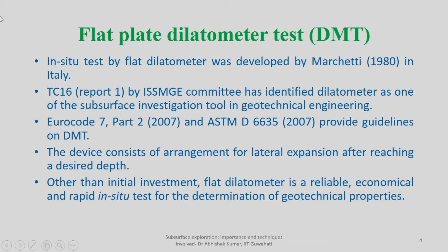The device consists of an arrangement for lateral expansion. There is a device which you lower depending upon the depth at which you are interested in finding the soil characteristics. You lower the test arrangement to that particular depth and find the soil characteristics by means of lateral expansion.